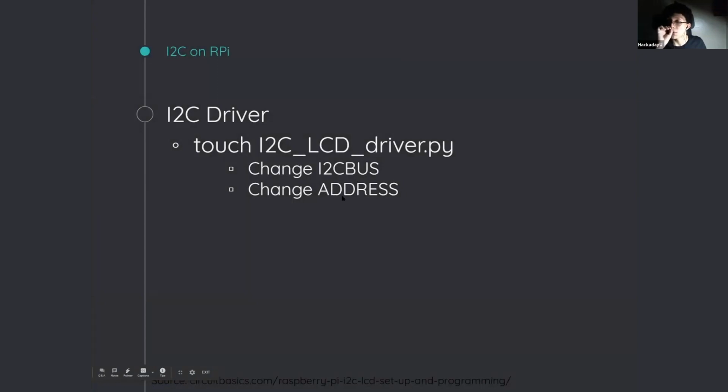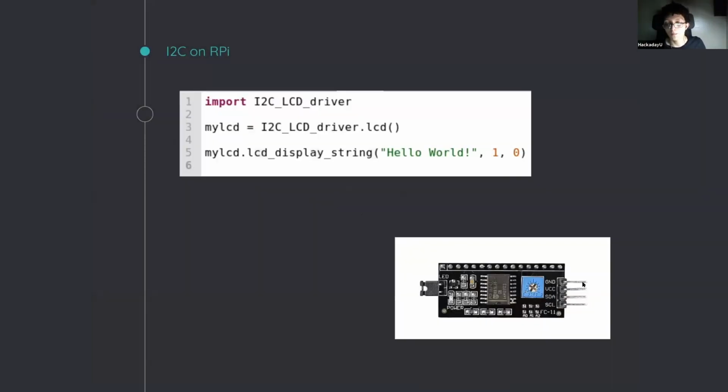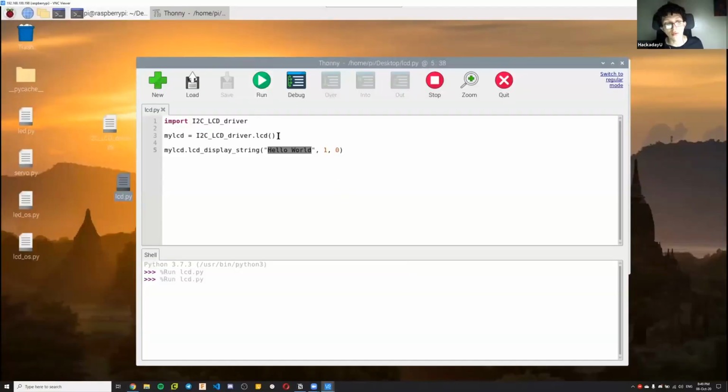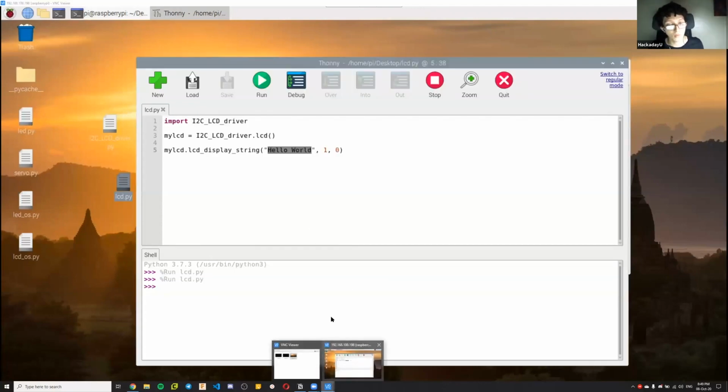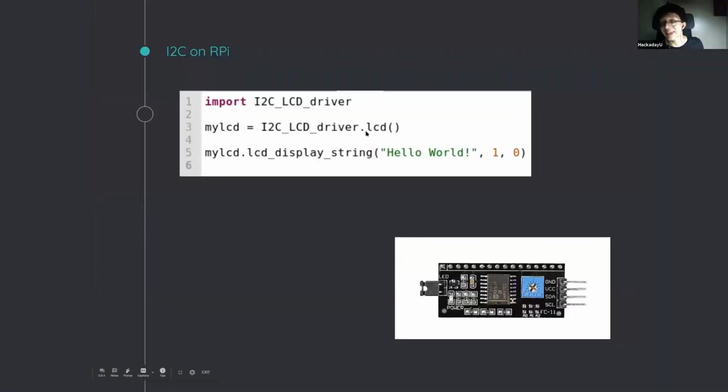And then the address of your I2C LCD. So this should run and it should show you a hello world. In case you're not seeing it, this is a potentiometer. This is the same device that we talked about that is inside a servo. This is basically a variable resistance, which you can use to signal that you're changing something, like a knob.